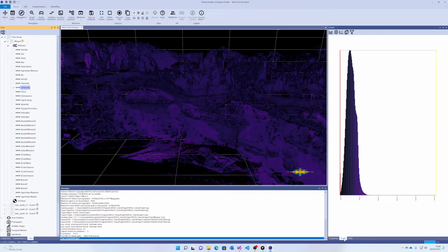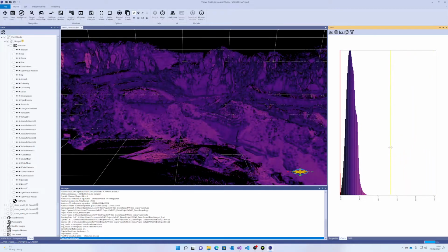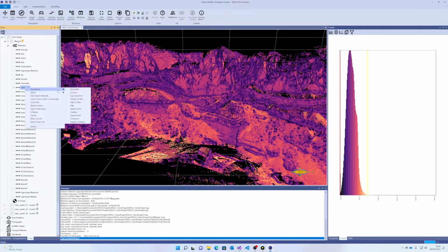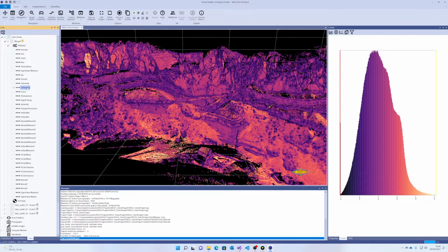If we've got our charts tab selected, if you don't see the histogram like this, you can just make sure you've got that button clicked, which makes this display visible. We can drag the filter bars so we can better use the color scale. And now I've got that, I'm just going to go into transforms on coplanarity and clamp the data to the filter. And then that gives us a better use of our color scale and a stretched histogram.